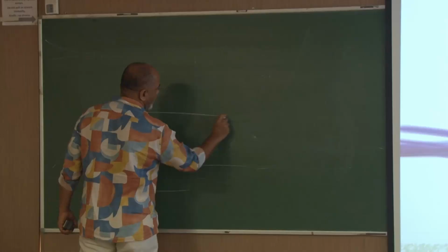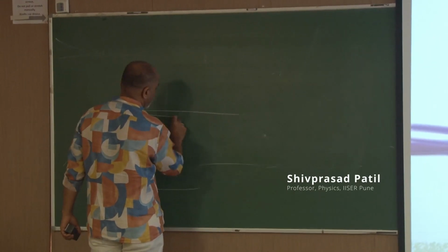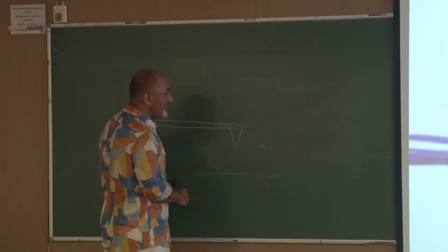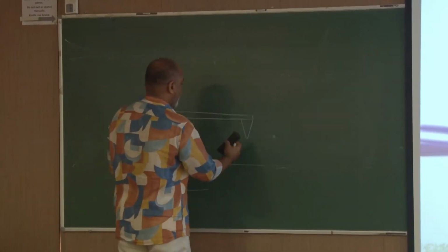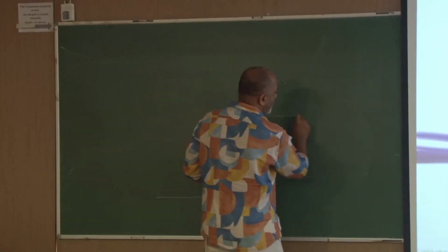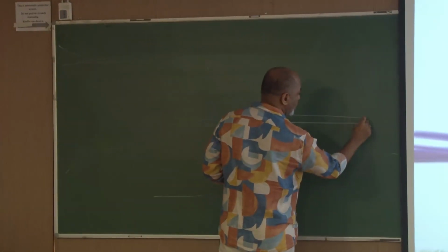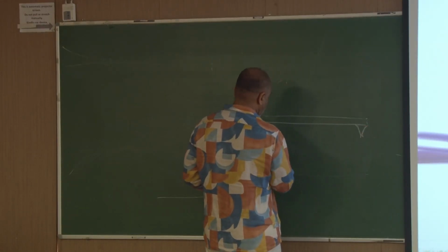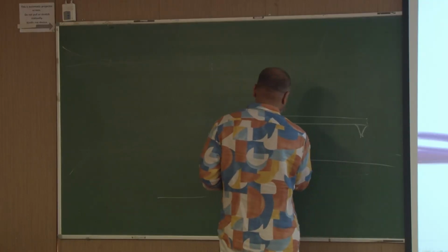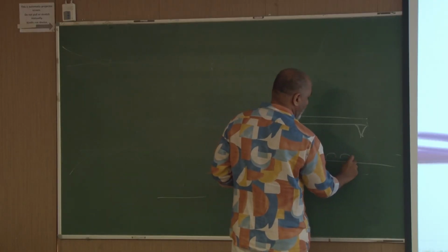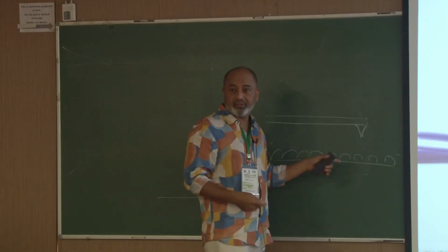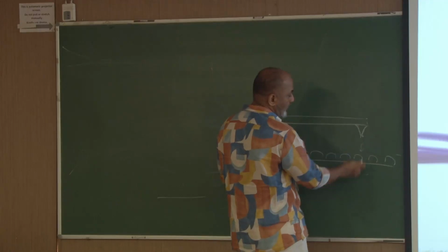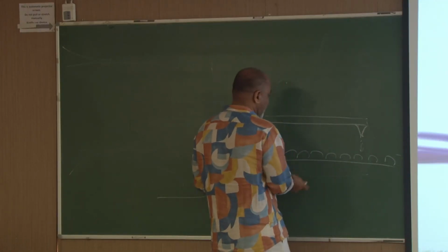But let's say this is my cantilever, the tip there. Can you see? Maybe you can come on. Actually, let me do it here. Okay, so this is my cantilever, let's say, with a diamond, whatever thing they attached, and you've got the surface with, let's say, this atomic kind of corrugations, atomic roughness in a way, and there's a tunneling current that flows back depending on the bias between tip and sample,